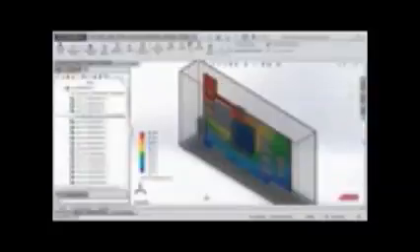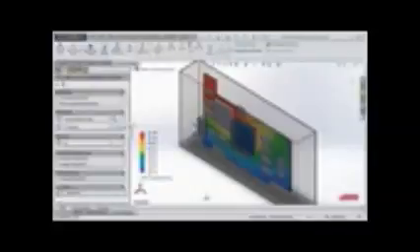Goals are automatically created when the board is transferred from Flow EDA Bridge. We will open a component and look at its properties. You can see under Convergence Control Goals that the default is maximum temperature. It might be that the average temperature in a part is critical in our convergence, so you can have it converge to the average temperature as well. You could also converge to maximum temperature and monitor the average temperature by activating it under Monitoring Goals.